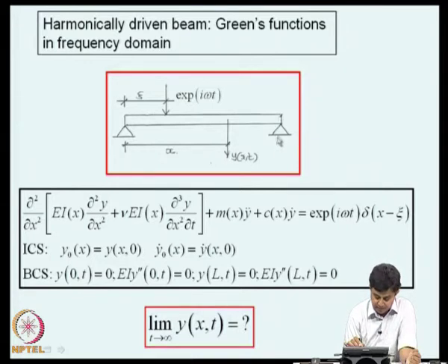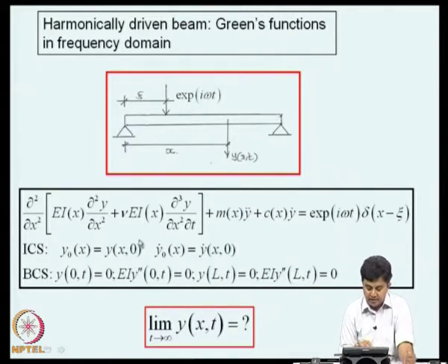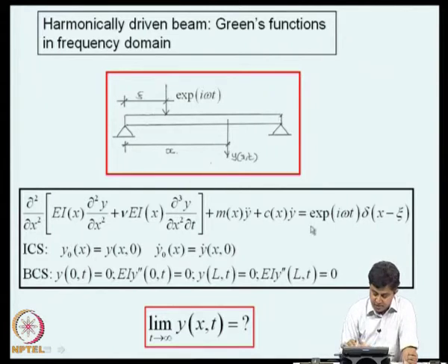So, we assume that this beam is driven harmonically by a force e raised to I omega t applied at distance psi from this end, and we are interested in knowing the displacement at a point x, which is at a distance x from this left end. So, the governing equation here is displayed here. The left hand side remains the same.